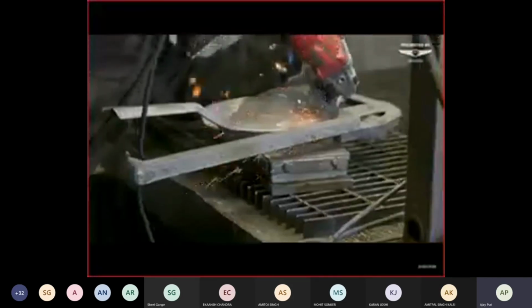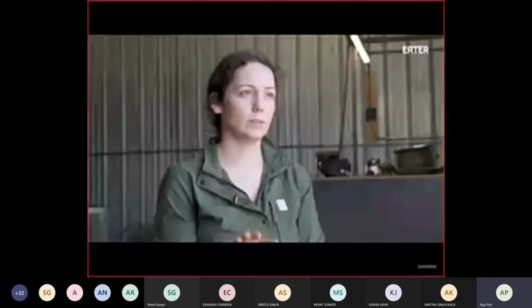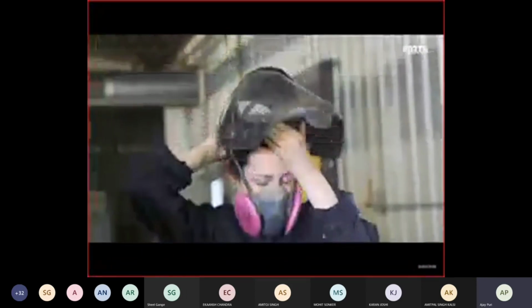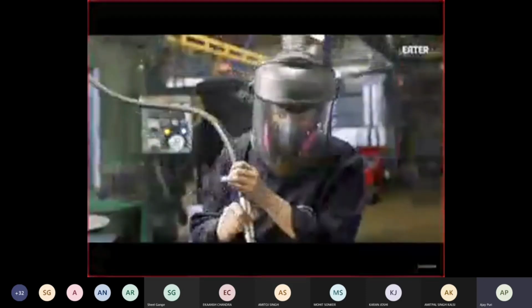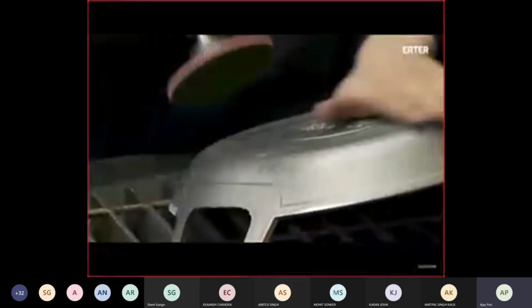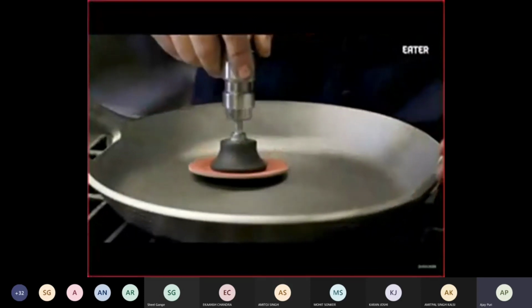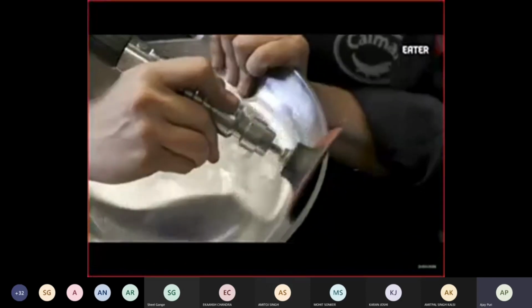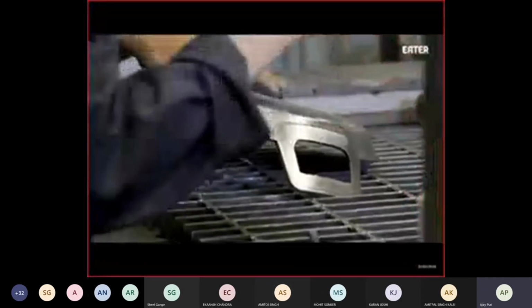After the skillets are cast, we take the surface of the metal down from its rough finish to a really nice smooth surface. You use different variations of sandpaper until it gets to the fine surface that you want.